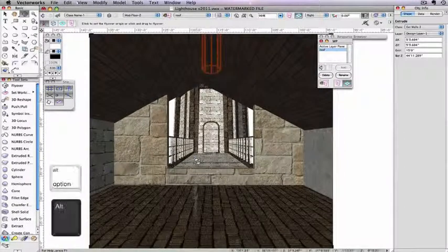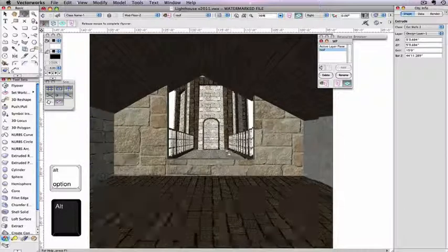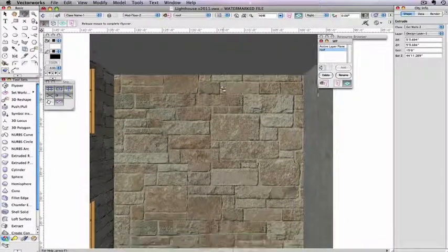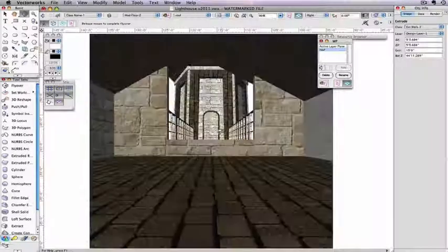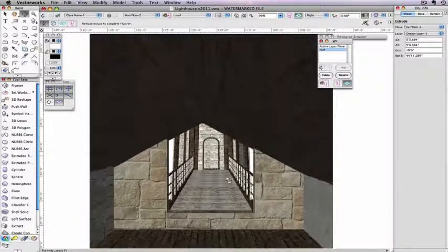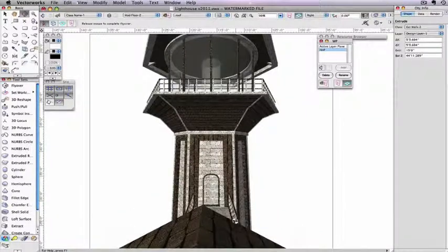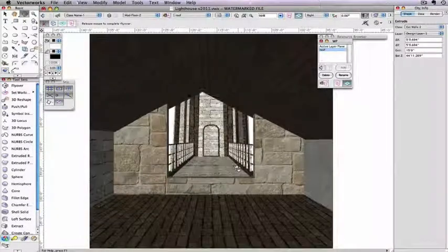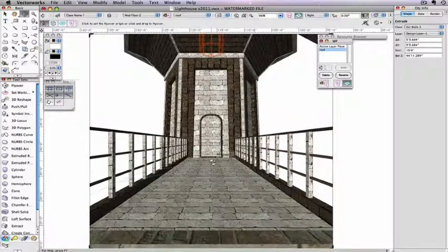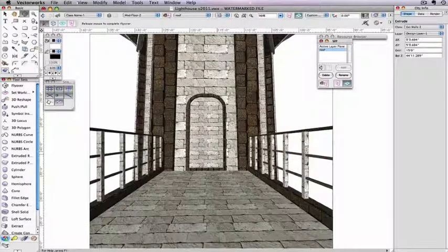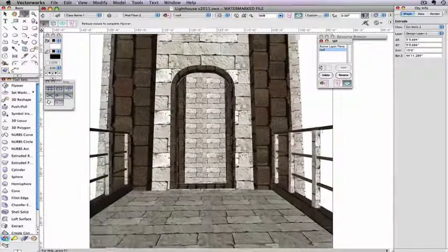Also, if you hold the Alt or Option keys and click and drag up, the observation point moves down towards the active layer plane, and clicking and dragging down moves up toward the active layer plane. You can see how using the Flyover tool will help you create views that you cannot achieve with the default orthogonal views to see details that may otherwise have been lost. It is an easy way to quickly customize views for presentation purposes.